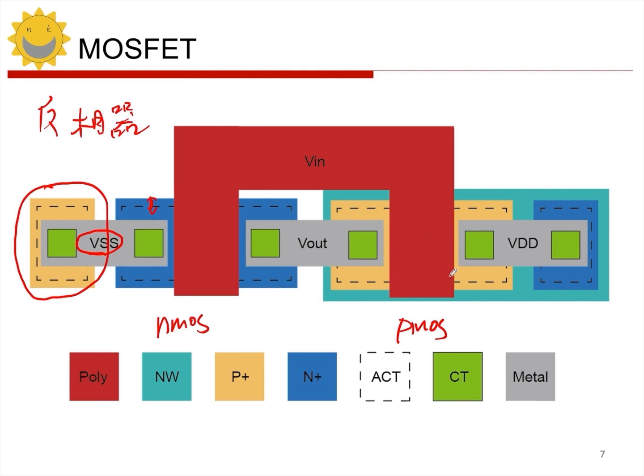The N well also needs to be biased, right? The bias for the N well is N+. So there will also be an active area along with the N+ doping. Now for the PMOS, its source terminal needs to be connected to the well. They are all connected together to the supply. Then we connect the two gates together, and this is the input. Then the two drain connection points are the output, right? This is a typical layout of an inverter.